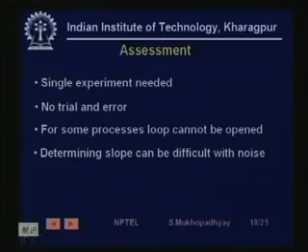Now some processes are already in closed loop, and you cannot open them. Nobody will allow you to open the loop and do an open loop experiment. So in such cases this is not applicable. And sometimes determining these slopes etc. can be actually very difficult, especially when you have noise.